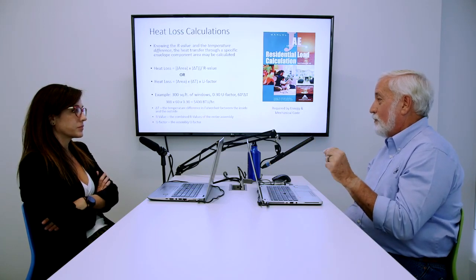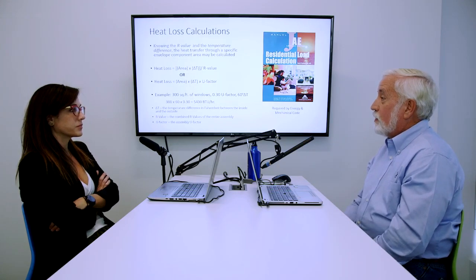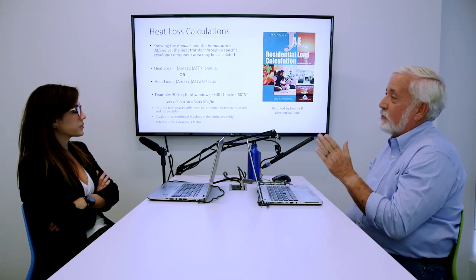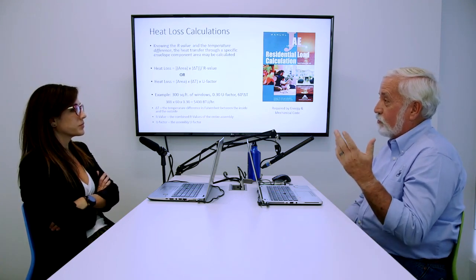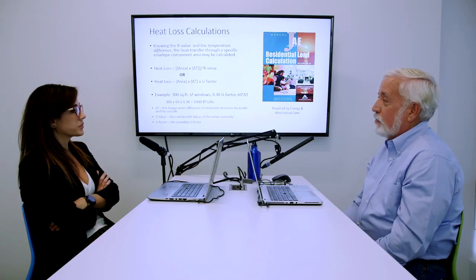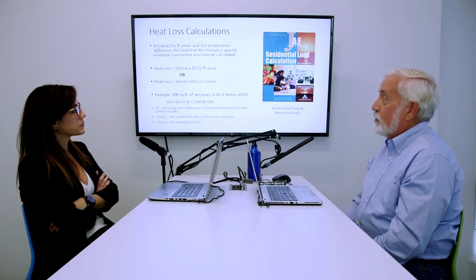Well, with improvements they've made over the last 8-10 years, it's real easy and real common to see 0.3, 0.32 on the windows. So they've dropped just little bits, just with the manufacturers improving their components. Still 2 panes of glass, still low E coatings. I'm not sure everything they've done to get there, but 0.3 is a good window.